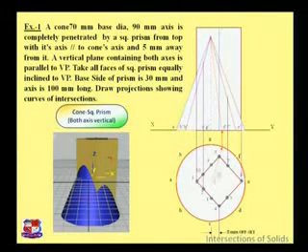from this point draw an imaginary generator. How to locate this O1 point? For that, draw an imaginary generator which passes through point number 8, meaning join 8 and the center of this cone with a straight line, extend that line, and from that line transfer this point to its front view. So this is an imaginary generator drawn in the front view. Now from this point draw a straight vertical line, and that will cut this line over here. Mark the points of intersection like this, 1, 2, and here similarly this point O3 is over here.